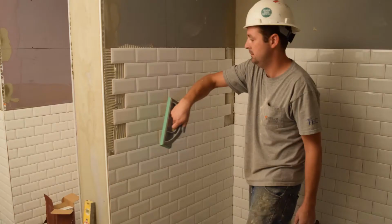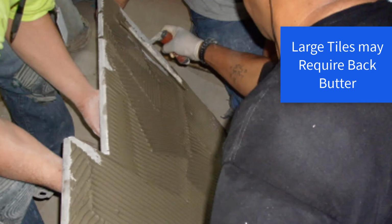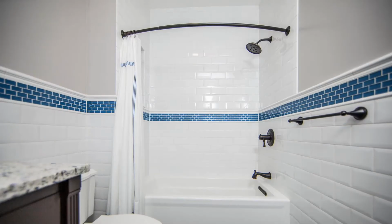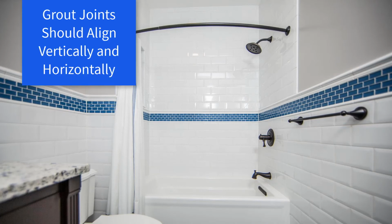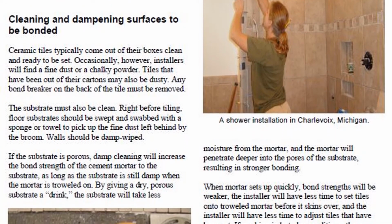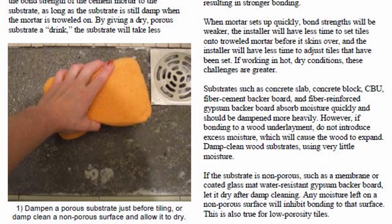To ensure a good bond, tiles that are 6 inches or smaller may be beaten in with a beating block and rubber mallet. Larger tiles may need to be back buttered to ensure a good bond. However, back buttering normally does not increase mortar coverage. When wrapping the tile around the walls and at changes in plane, all grout joints should line up, both horizontally and vertically. In addition to this video, we strongly encourage you to thoroughly read and understand Chapter 10 in the CTI manual. We wish you well in your testing process.